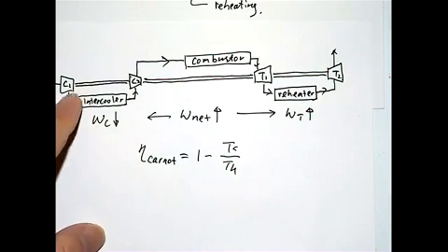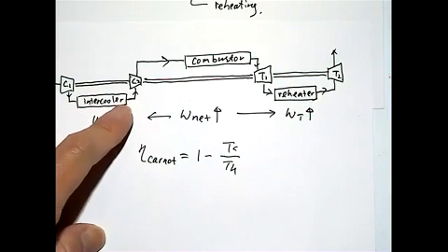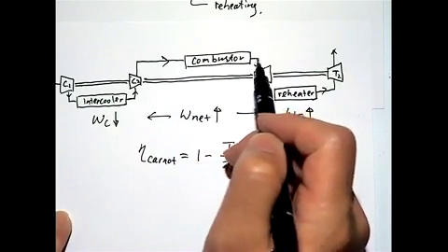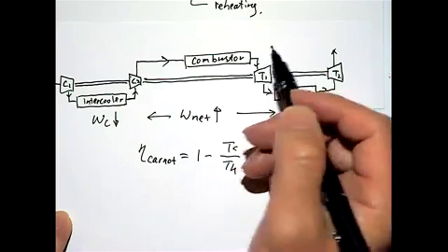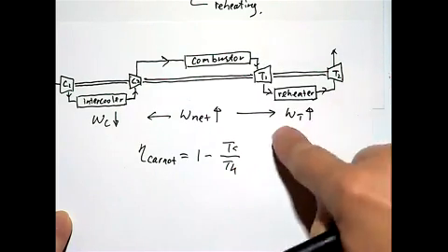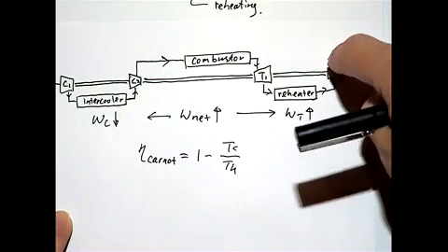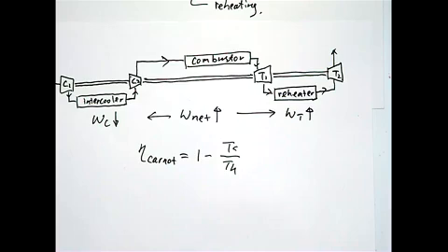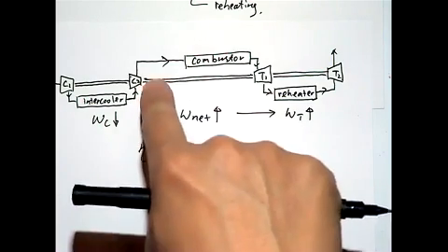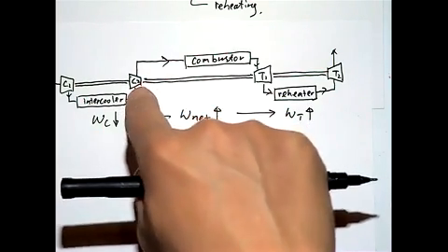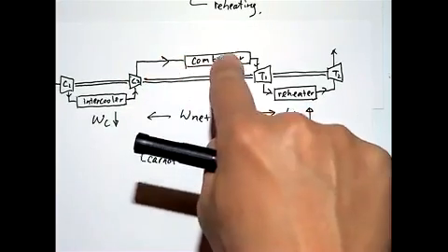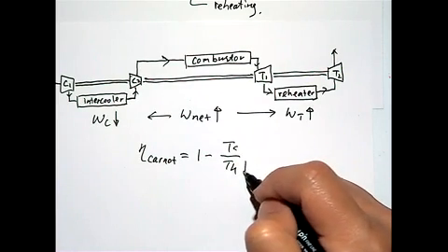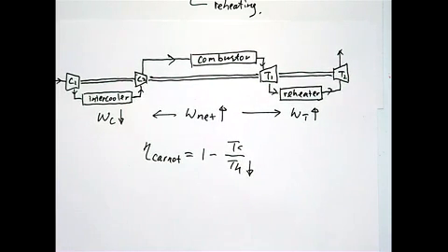So by putting an intercooler here, so the T_H is here, right? T_H is the temperature leaving the combustor. That's the hot temperature, and the T cold is the temperature leaving the turbine. By putting an intercooler here, you drop the temperature getting into the second compressor and drop the temperature getting to the combustor eventually. So you reduce the temperature of the hot reservoir.